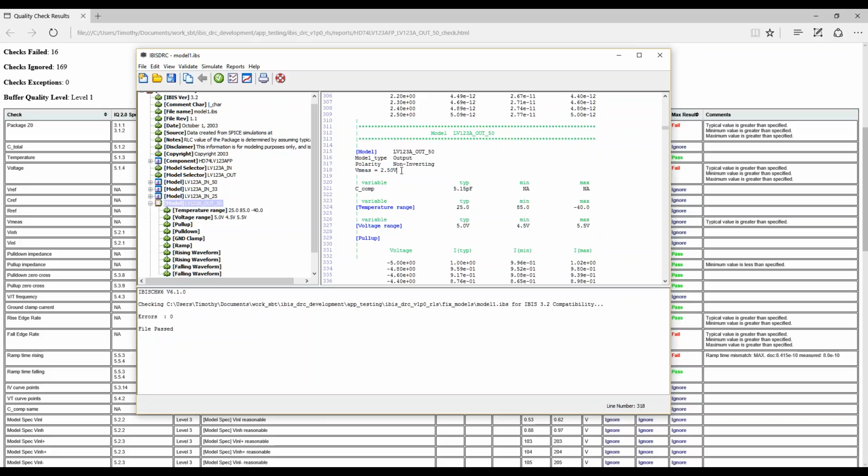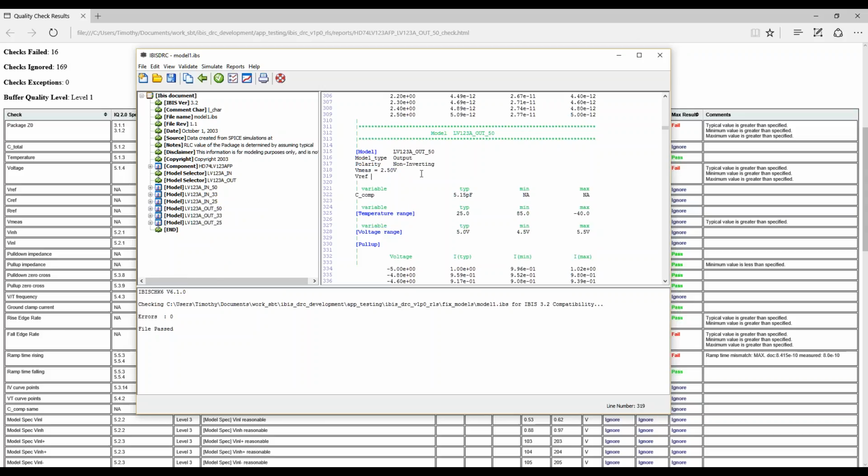Some tools might give you an error. So when you're doing your flight time delays, this is going to potentially give you some problems. Now you can see that the IBIS tool doesn't give you a warning or an error on it. The IBIS parser has its own subset of rules, whereas if you put different values in here, it'll give you some rules.